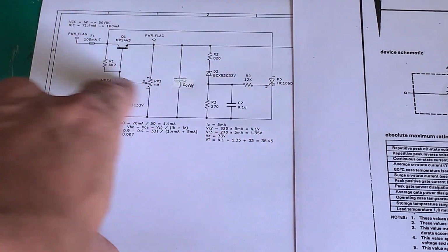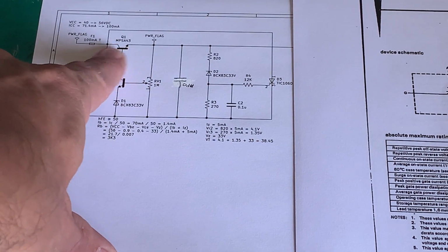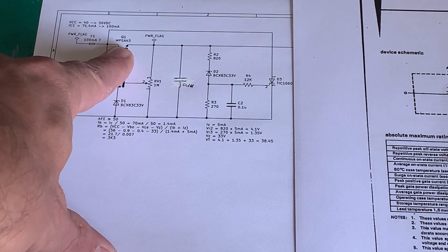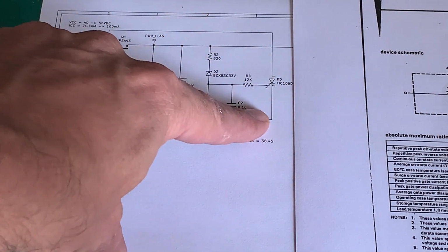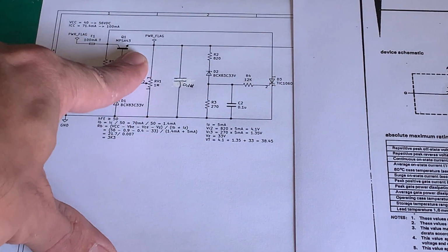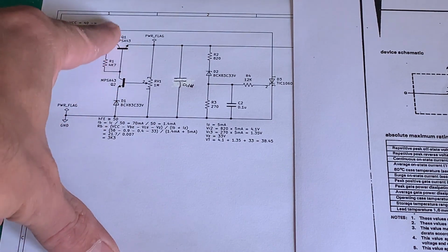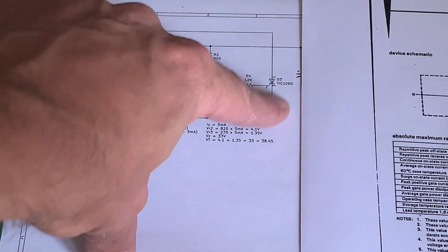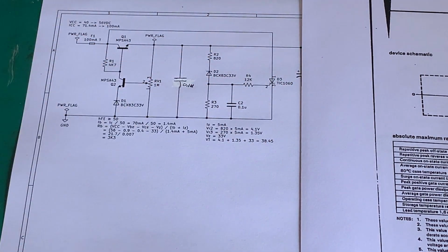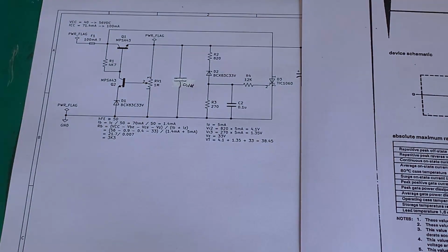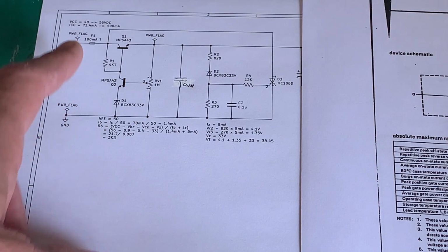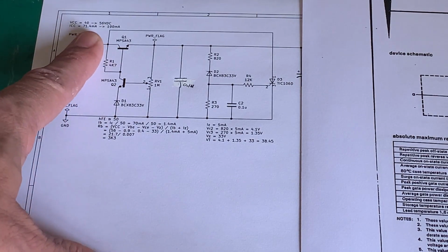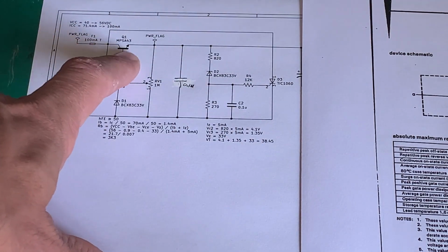This is in the case really if this transistor fails and fails in a short. So if it fails as a dead short, our crowbar will kick in and will pull the current through the fuse, through the top line, through the SCR to ground. Nice and simple. Of course, under normal circumstances this will not trigger.